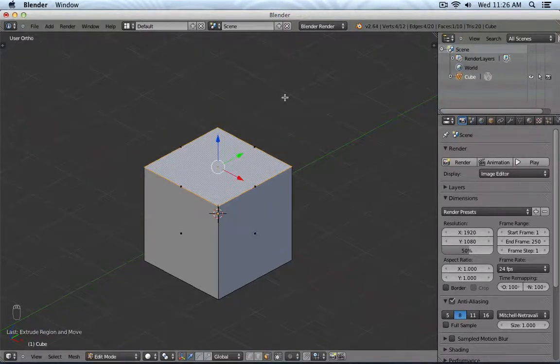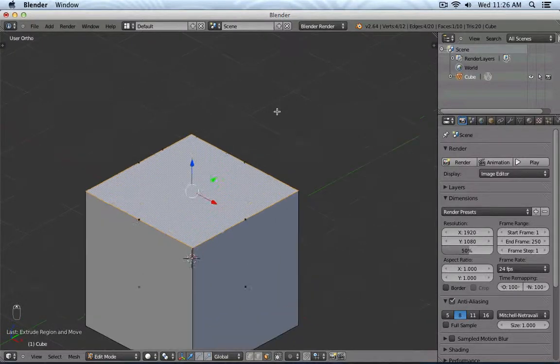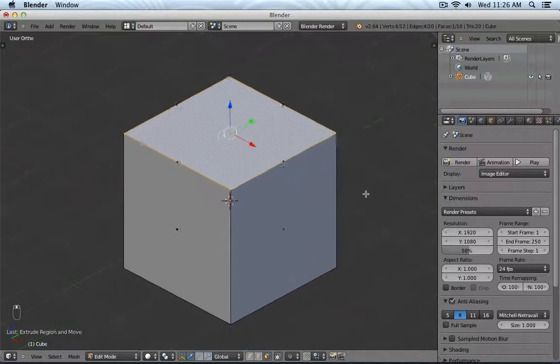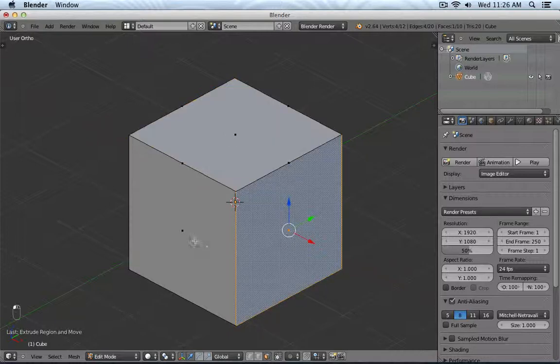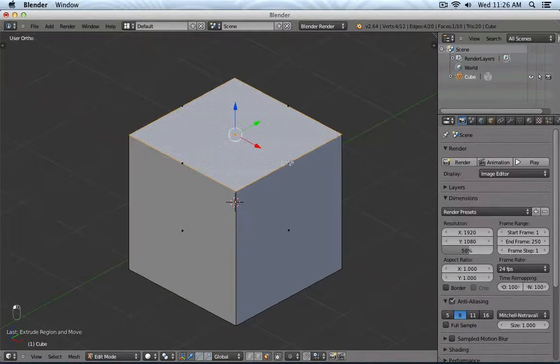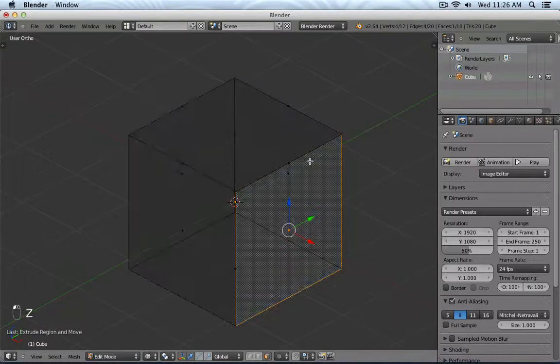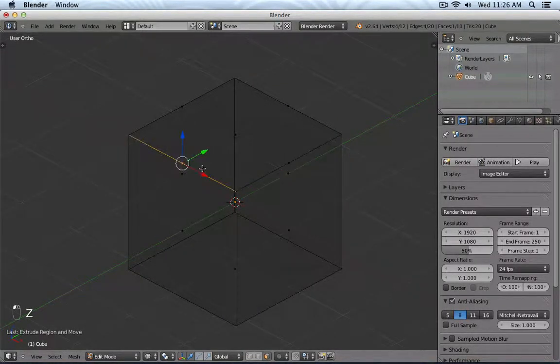And if I press Escape, I don't really want to actually move my face. I just would like to extrude it out. So extrude out means it generates immediately the faces in between. You will also see that along those red lines, there are small black filled rectangles. And those rectangles are the icon to indicate that there's a face. You see here is a rectangle as well. So all those are faces. And here, I can't really click it right now, I think. Yes, actually I can in shaded mode. Sorry, wireframe mode. There are faces as well.